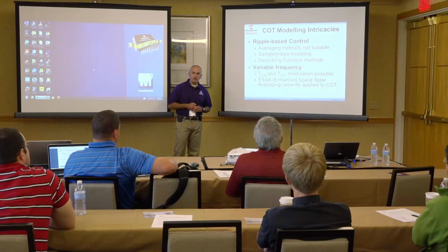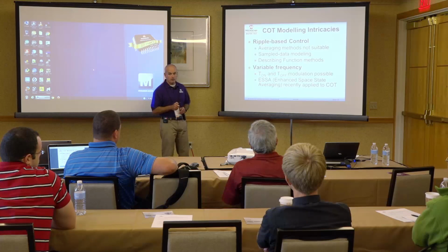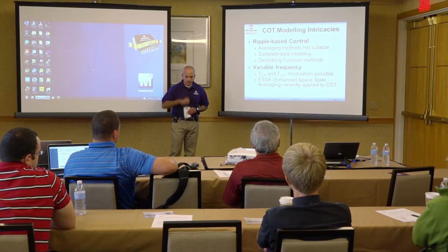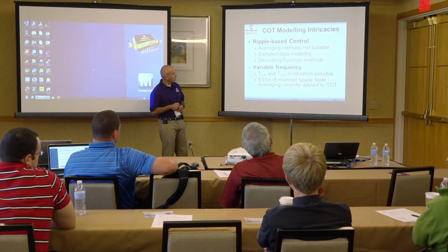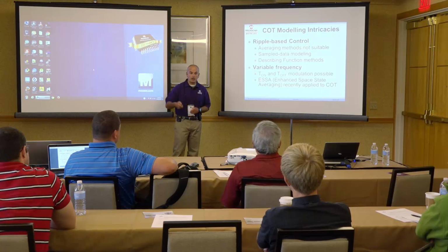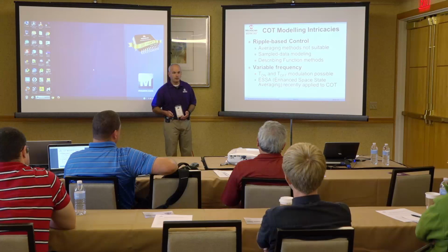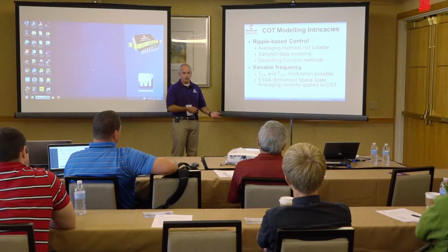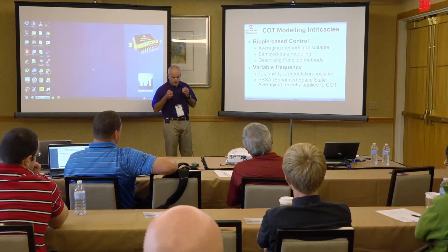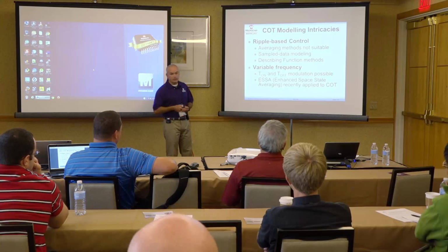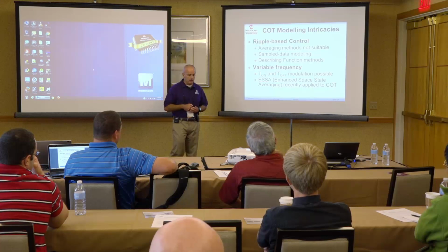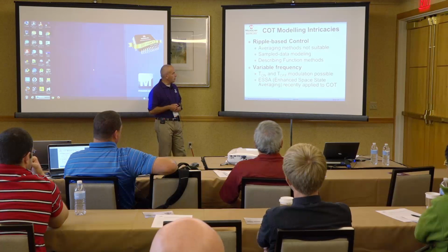Ripple-based controllers are not easy to model at all, because all the, let's say, legacy averaging methods we have to analyze switch mode converters, like, for example, the PWM switch model, work by removing the ripple. Now, we cannot apply this method if the ripple is so important to the regulation. There are alternatives to modeling of ripple-based controllers.